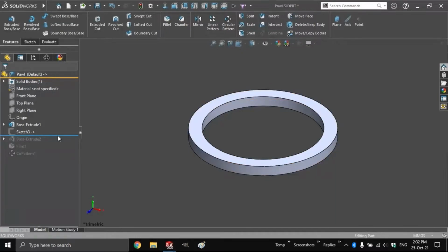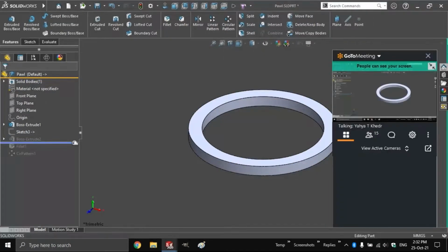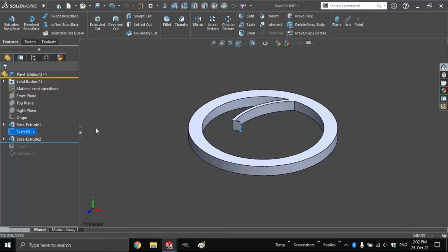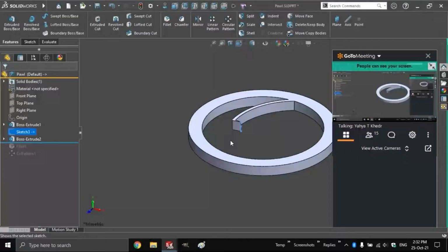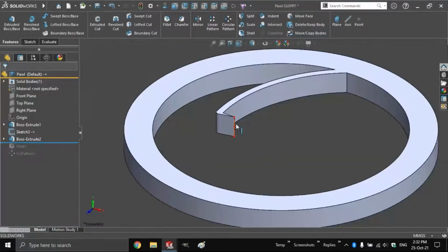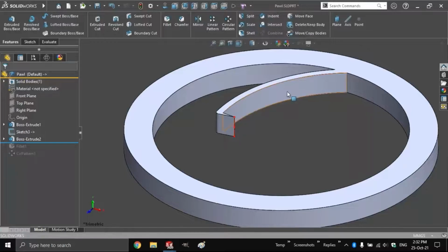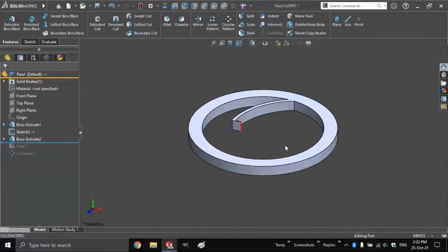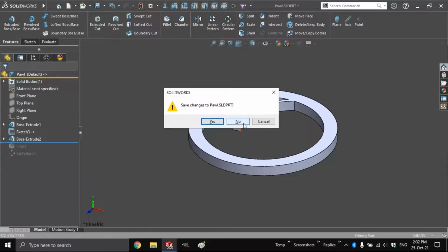So if I go to the second feature, I just extrude this, but let's just change the color of this real quick, of sketch 3. Let's make it red, for example, and let's show it. So you're going to notice that it actually extrudes all the way to that sketch I made. So if that sketch, for example, changed its position, if that sketch actually moved, this arm will actually move too. So that's the base of my animation. That's what I made. Let me just close this.